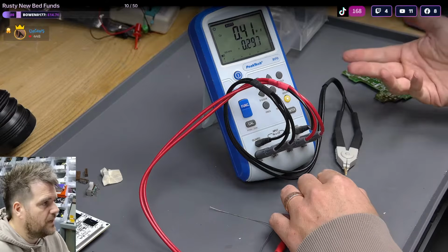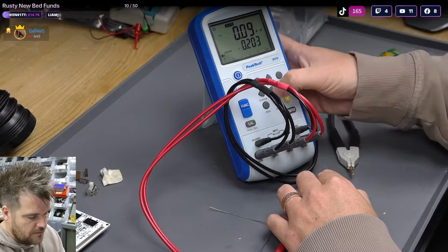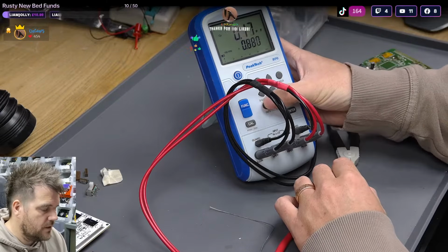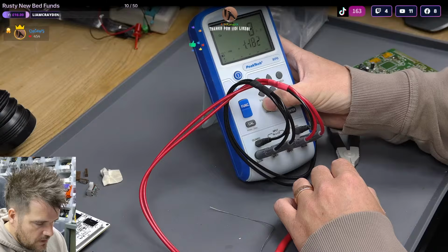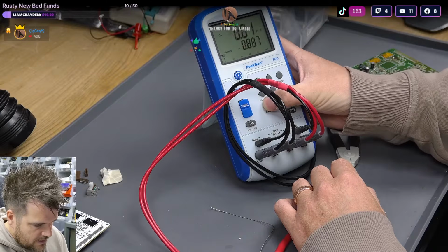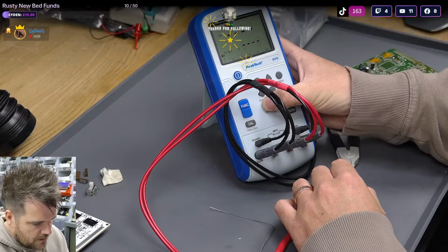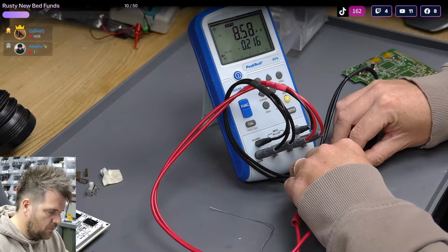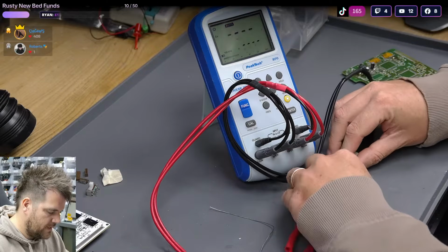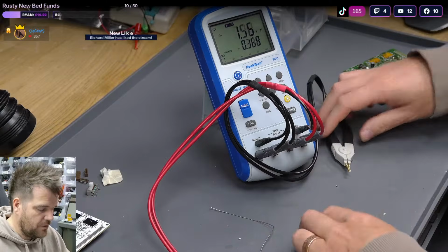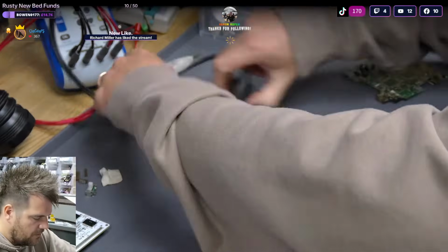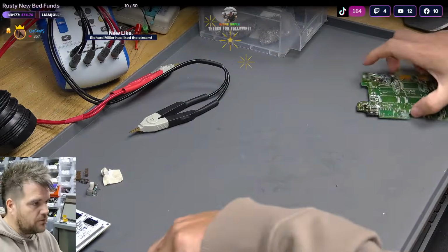It's going to be 100 nanofarad and it's just reading slightly over, because the idea of 100 nanofarad is to filter out high frequency noise. I think 100 kilohertz is the highest test this goes to anyway. That's why it's tested at that. It's reading 0.11, but it's not going to be 0.11, it's going to be a 0.1 microfarad, so 0.1 uF. Very common, that's for filtering out high frequency noise.